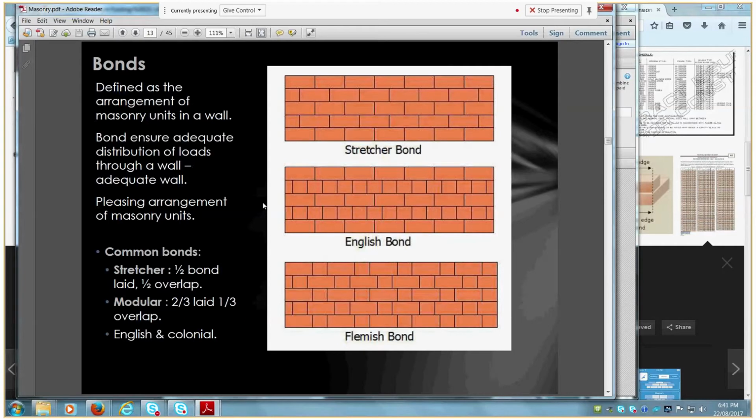And so you have insulative requirements; we're in climate zone 5. I think it's getting up to about R2 for your walls, or R1.8 I think. So you've got to get that insulation in there somehow to your external walls to meet the requirements of the National Construction Code for climate zone 5.